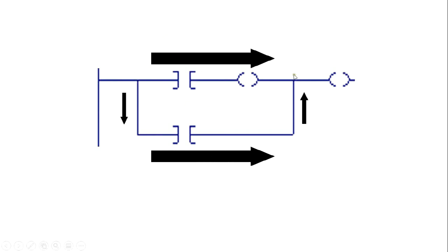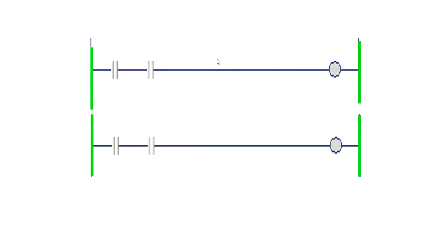It will go through the rung first, and if it isn't energized, it will then go through the branch. And you will notice on the rung we have two outputs in series. This isn't normal in a conventional PLC, but it is fine in Logix 5000. It works beautifully.